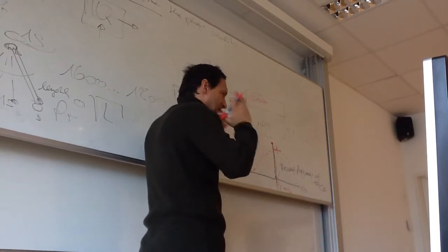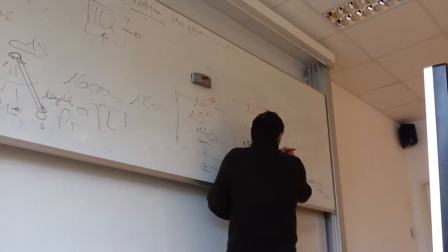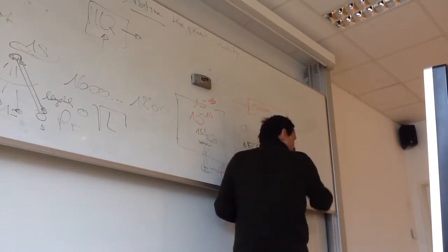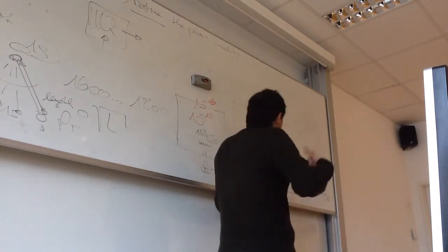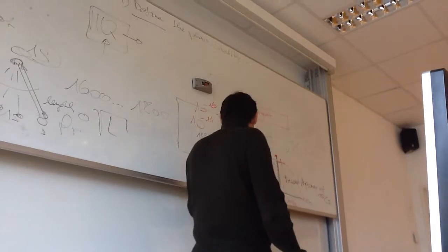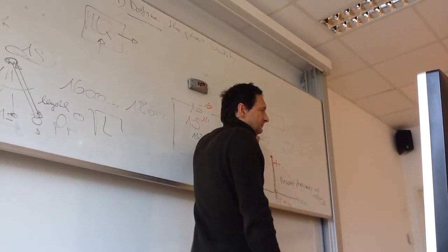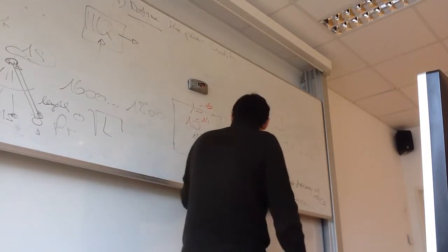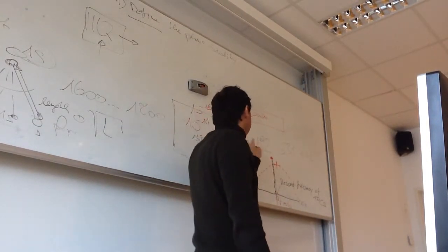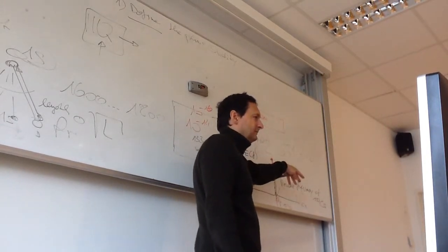And here you will stick your frequency counter. So the frequency generator just is varying a little bit around that peak. So it's more or less locked to the resonance frequency of cesium. So this frequency generator is locked and it runs with a frequency of 9,192,000,000 hertz.